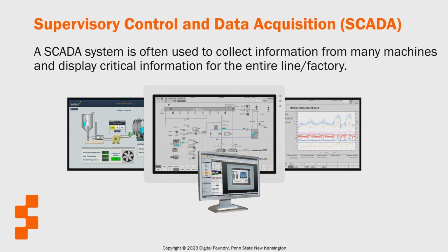Supervisory Control and Data Acquisition systems, or SCADA, are used for controlling, monitoring, and analyzing industrial devices and processes. The system consists of both software and hardware components and enables remote and on-site gathering of data from the industrial equipment. SCADA systems are designed to collect field information, transfer it to a central computer system, and display the information to the operator graphically or textually, therefore allowing the operator to monitor and control an entire system from a central location, in real time.